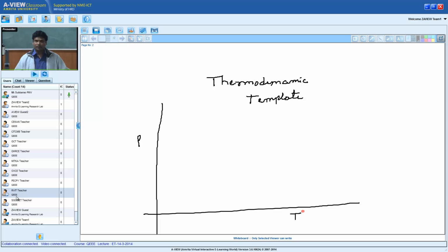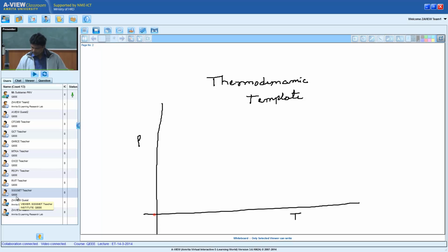And it is good that because of Lord Kelvin and Torricelli, we got two absolute truths about this particular template. Torricelli proved that there is a zero absolute pressure, below which there is nothing negative. The great Kelvin proved that there is a zero absolute temperature, there is nothing above. What does it mean? My entire knowledge about the substance is only in this direction. So this is called a quarter infinite domain in which you need to define the substance.